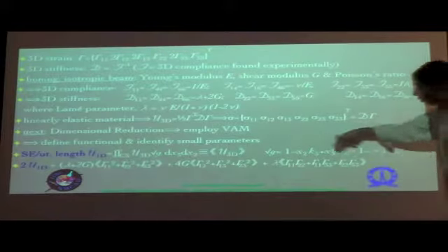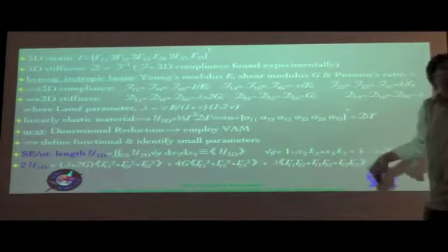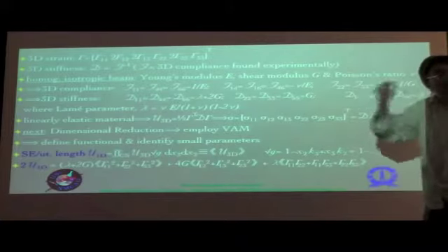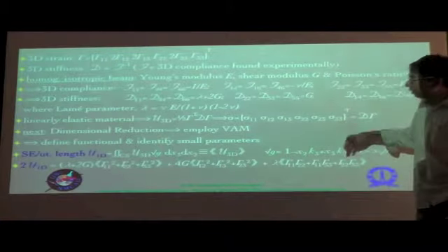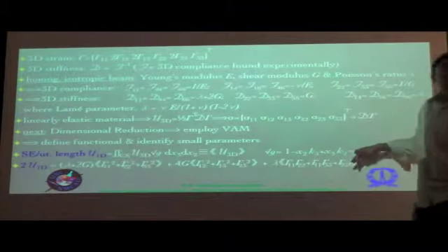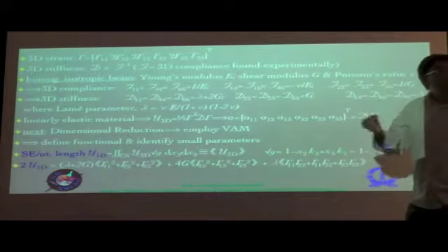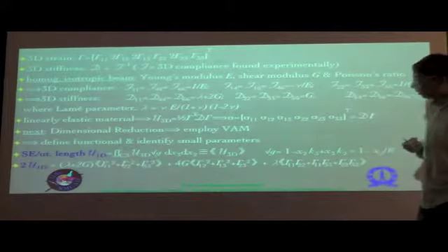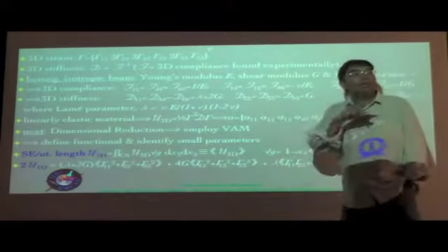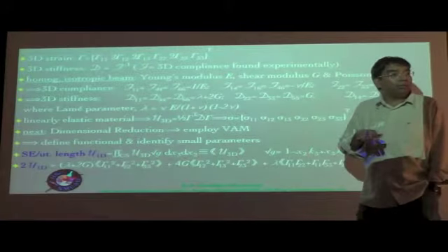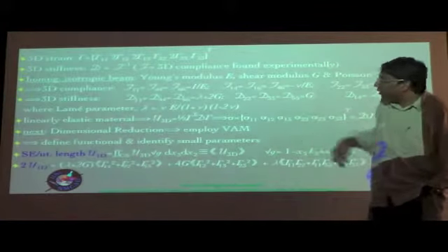So we have this. Of course, we now need to substitute for the expressions that we have for the gammas, which we have already derived. So again, this is the overall U1D. Then we'll talk about a U1D naught, which is the leading terms of that, the zeroth order approximation, where we'll take the terms which we did not underline in one of the previous slides. That will give us the leading terms, and then we have to minimize that, or in other words, determine its stationary points with respect to the warping.